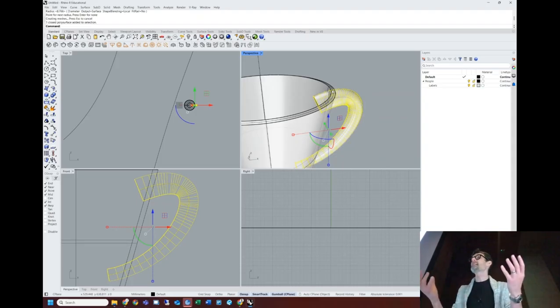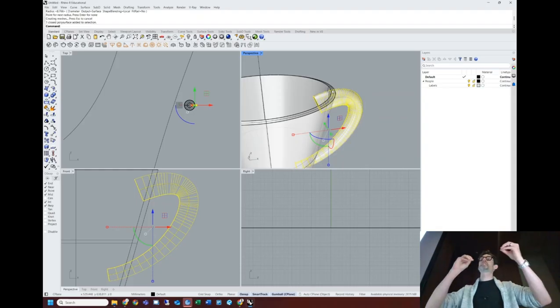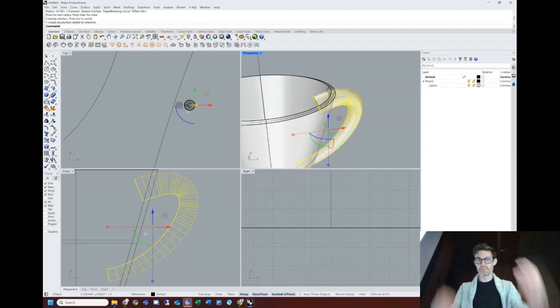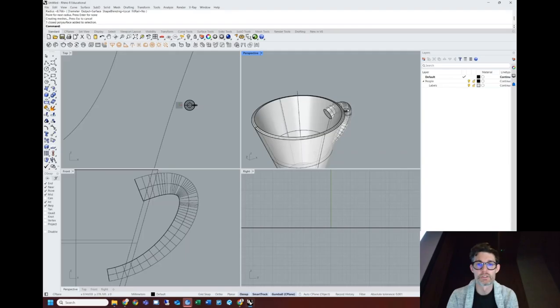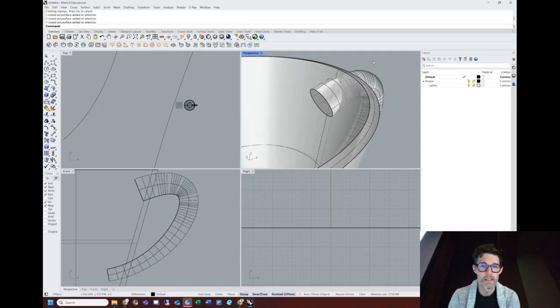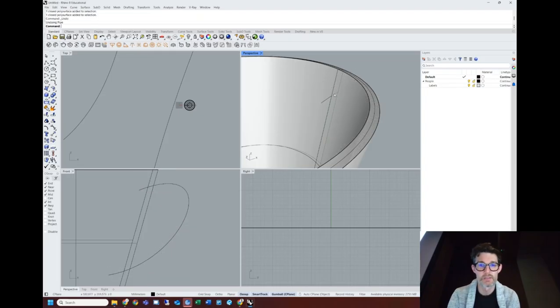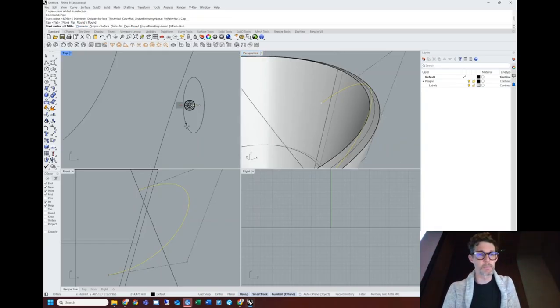So this is a perfect place to use the same techniques that we used last week, which is our Boolean operations, where we can start to carve out one thing with another. In order to use Booleans, these shapes need to be what's called closed. So this is a closed polysurface. The reason I'm sure it is closed is because when I made this pipe, I made sure that there's this thing called cap, and that puts a cap on the end of my pipes. I could actually do a round cap, which is kind of fun.